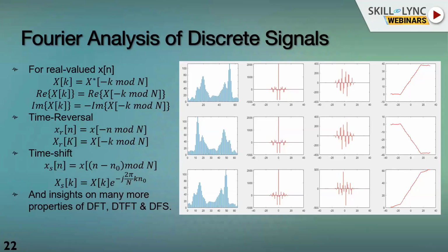Now, if we take the route of finding the impulse response of the system first and then analyze its frequency response behavior, it can sometimes become very complicated. So Z transform comes to our rescue in these situations, and using it, we can directly map the CCDE to the transfer function and then understand the frequency response without the need to compute the impulse response of the system. So this kind of analysis is very easy through Z transform. That is why it finds a crucial place in fundamental concepts when we are talking about DSP.